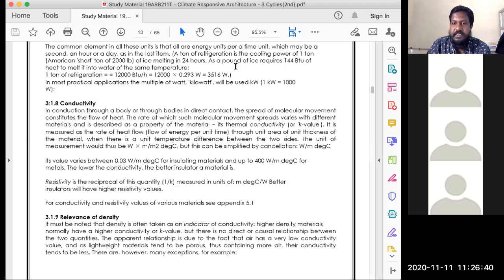So in this case, those materials can be avoided to achieve better thermal comfort in hot zones. Imagine if you have higher conductivity. My example is, I'll compare a brick wall to just a steel sheet. It could be a container. The steel container is what we are using for a cafe exercise. If you are using a brick wall, the K value of brick is much lesser than the K value of a steel container.